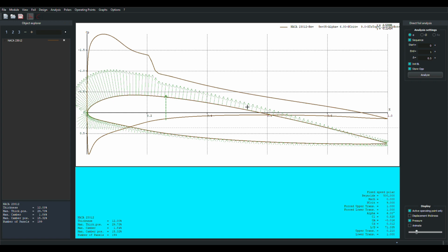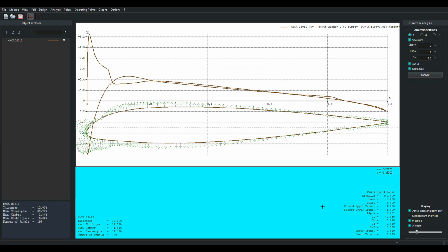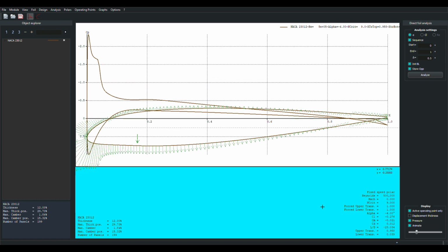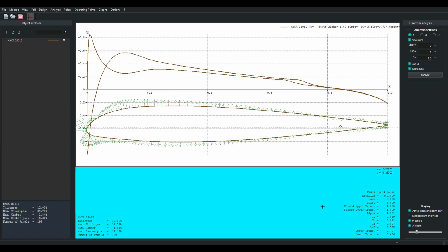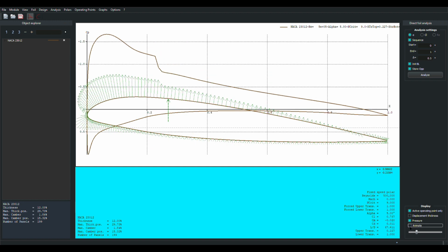Okay, so next I'm going to take a moment here to set a 20-degree flap on here, and we're going to take a look at the pressure distribution for that. And as we close out this segment, I'll just animate it through its angles of attack, and you can see how the pressure distribution changes as we go through those angles of attack. And let me stop it here for a moment and mention one other thing. Right back here, you'll notice that there's a swap in pressure distribution.